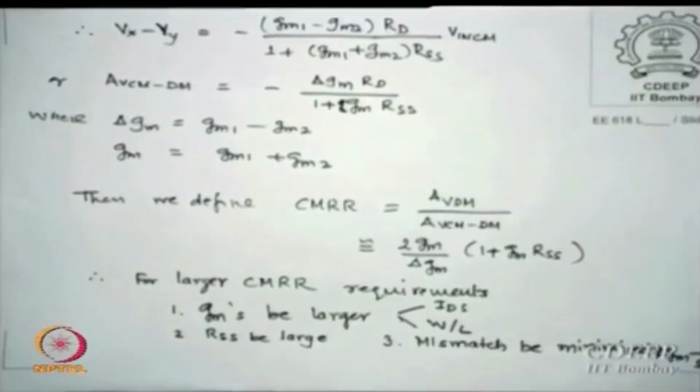So there is an issue of how much CMRR I should be allowed, so that I get the other performance also as good as I want. That is the design issue, is that clear? CMRR is therefore kept a flexible term; they say minimum CMRR should be 80 dB. You are not saying 120 dB, because otherwise you cannot design it.